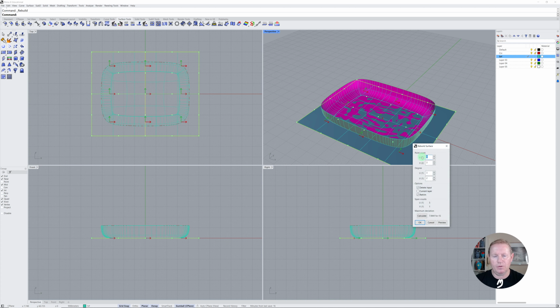When I click on this surface and I come across here, I can turn my control points on. And to help myself, I'm going to shift this surface to layer 5, change object layer, and I'm going to activate that layer, and I'm just going to hide my surface layer and my curve layers for now. Alright, so here's this surface, and if I grab these 4 control points,